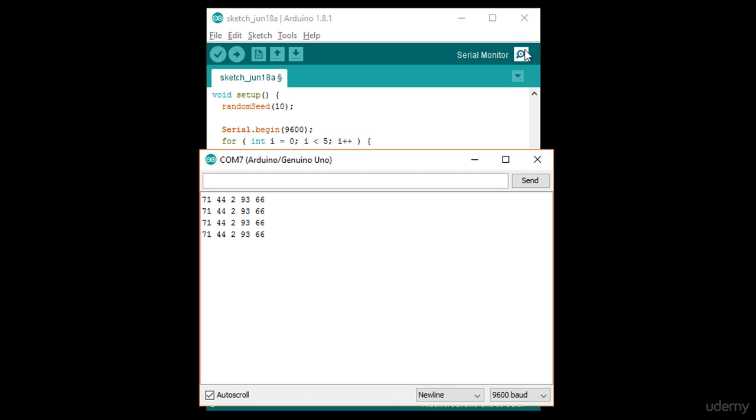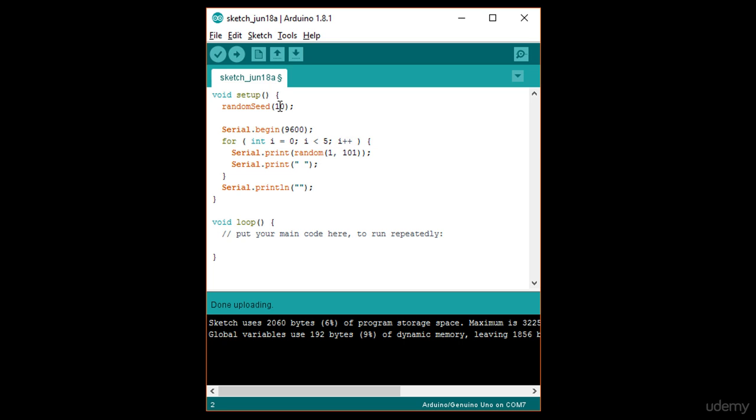This isn't an easy problem. In order to generate truly random numbers, we need a truly random seed. One trick we can do in the Arduino is read the voltage from an analog pin that we're not using. If the pin isn't attached to anything, we can consider it floating, which means the voltage is unknown. Due to the internal workings of the Arduino, it's likely to be somewhere between 0 and 5 volts. But we have no clue what that value might be.